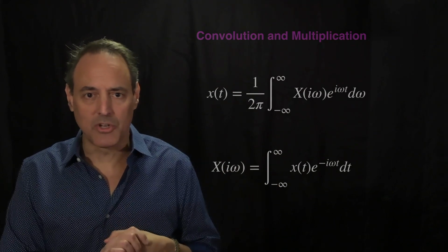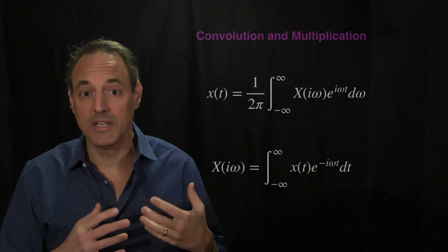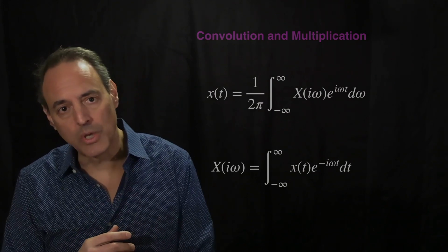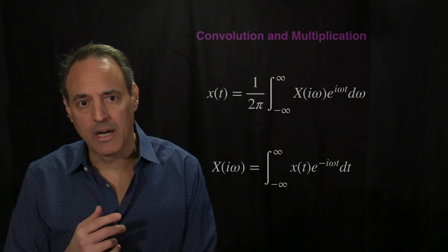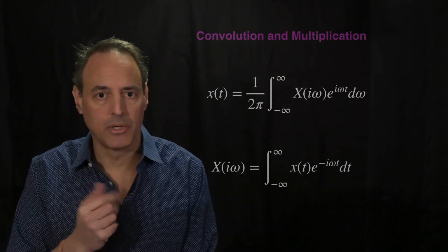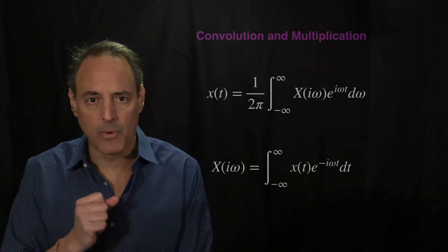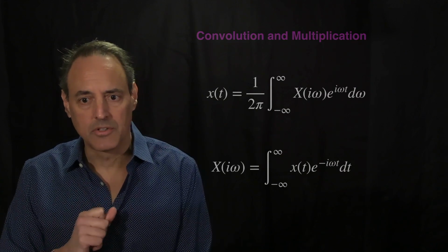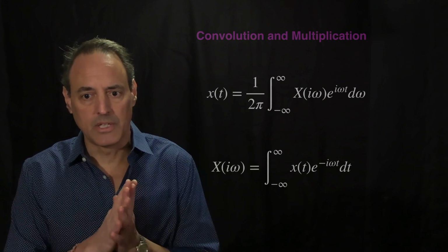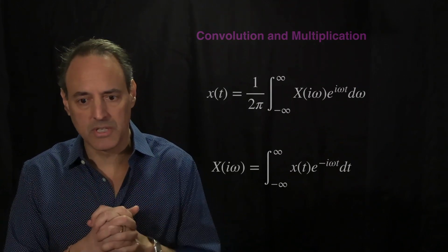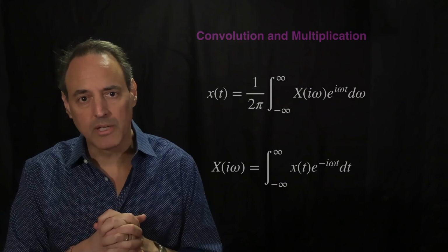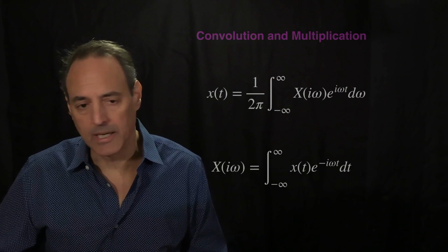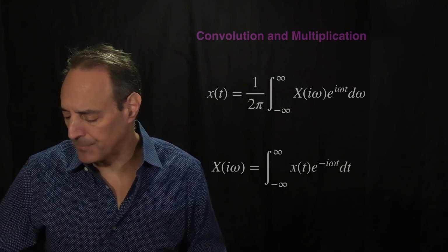In the last lecture, we talked about things like, for instance, differentiation is very nicely done in the Fourier domain. And so we can take advantage of that in doing operations to our signals. And in here, I want to highlight one of the operations we're going to use all the time, and it's going to be related to convolution. In fact, convolution or multiplication of signals is going to be something really important for us in terms of basic signal processing design and applications.